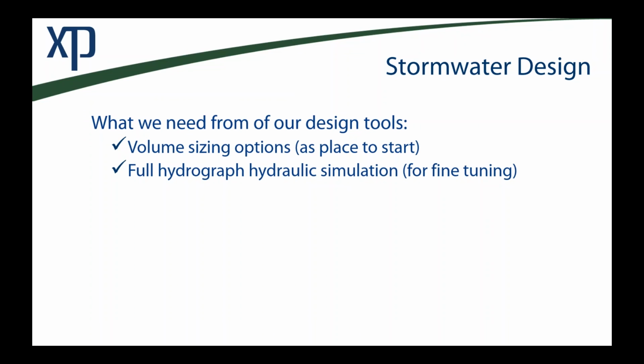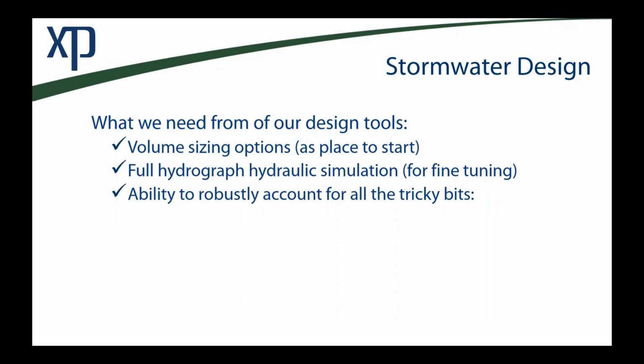So you can get away with not doing a lot of volume sizing to start with, but really you have to have a full hydrograph system. The other piece here is the ability to robustly account for all the tricky pieces. So we're talking about the water quality facilities, infiltration items, complex outlets. So water quality facilities in particular, we'll look at this later on.